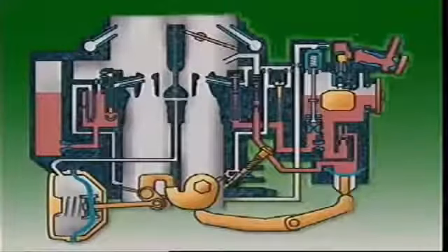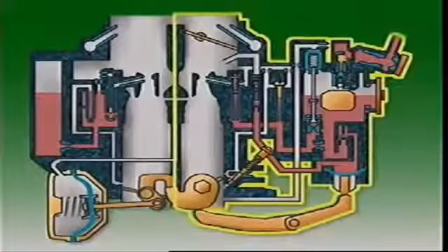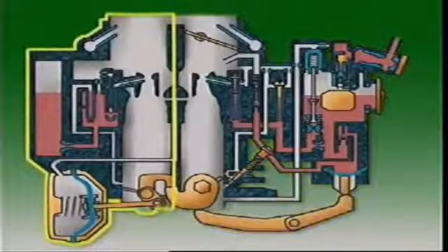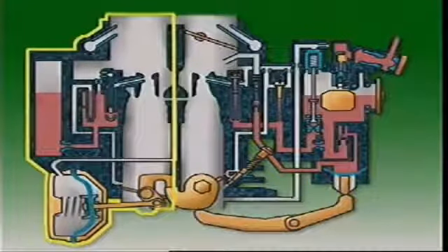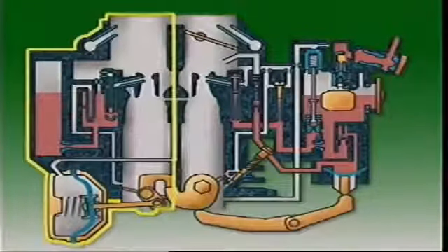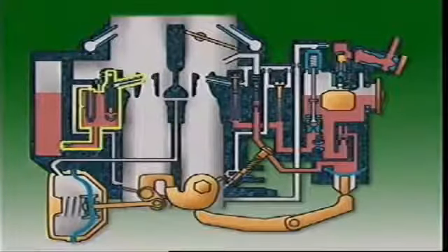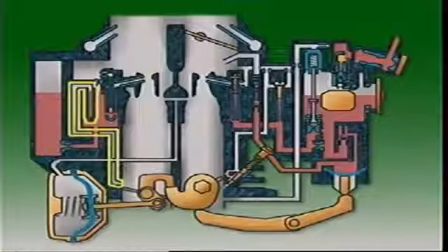One half of the carburetor has all the circuits needed to supply mixtures for the whole range of operation. This is called the primary side. The other barrel, the secondary side, supplies extra mixture but only at high speed or full throttle. It normally has a main metering system and a non-adjustable idling system.